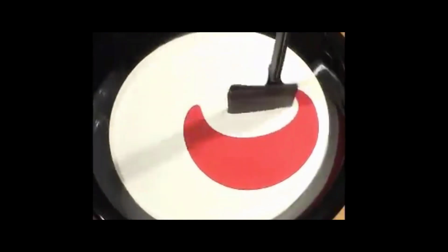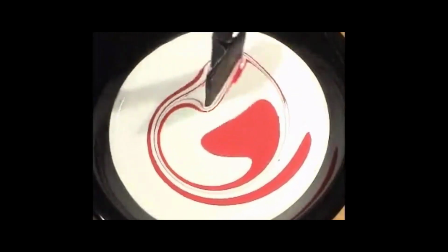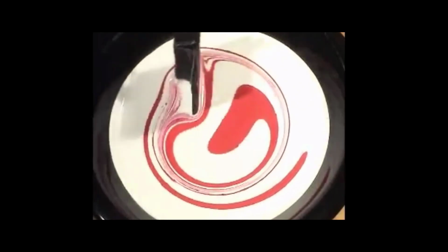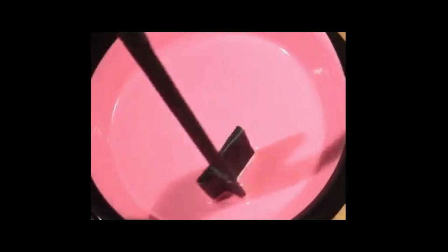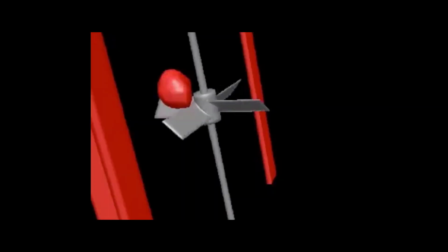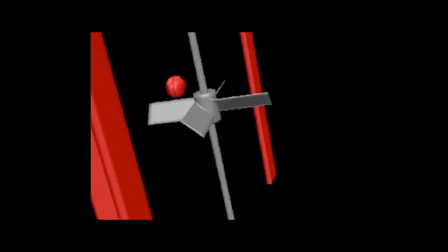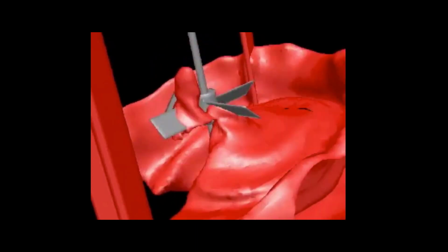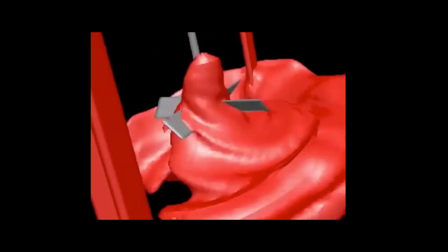Here we observe the mixing of red and white paint stirred by a paddle. The flow is self-visualizing because the paint pigments reflect different colors of the incident white light. Eventually, given enough stirring, the two pigments become well mixed on a molecular scale, and we observe an intermediate pink hue. Similar mixing can be visualized in a computational fluid dynamics, or CFD, simulation by marking a blob of fluid particles red and following the distortion of the blob. For visibility, the red pigment is shown mixing with a transparent fluid.